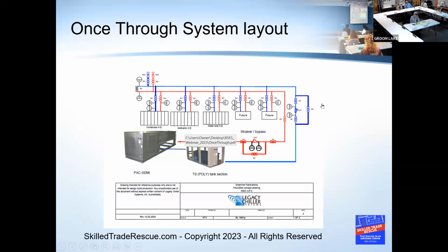I had that exact same scenario once, and there were actually flow meters on each of the branches. It was in a metal stamping plant where they had a bunch of machinery. The whole plant shipped over from Germany. They only had a 5-degree temperature drop across the chiller, all kinds of heat coming out the condenser. Everybody was saying that it was low on charge. Yeah. Running all the way up in RLA, and none of the flow meters are reading anything.